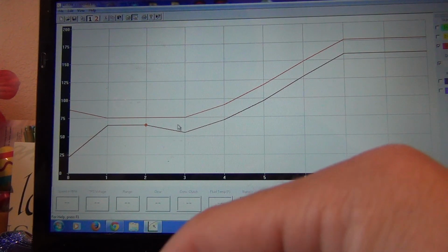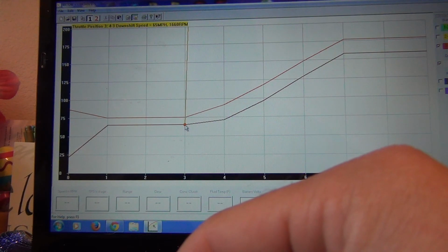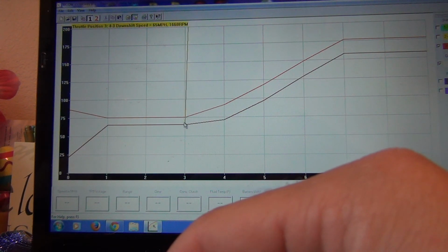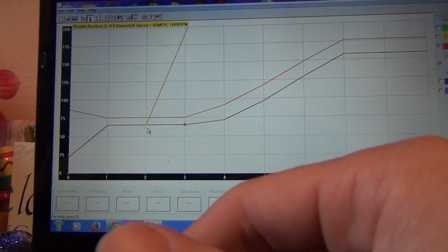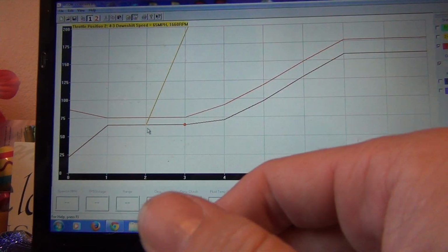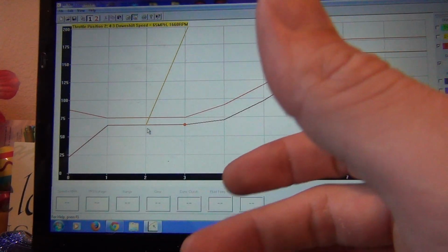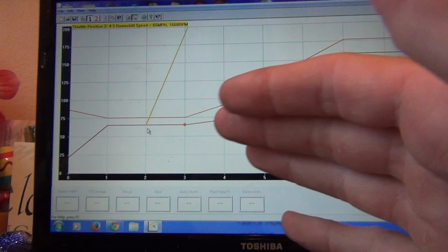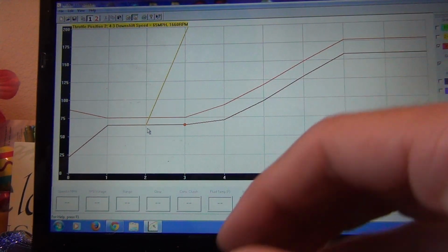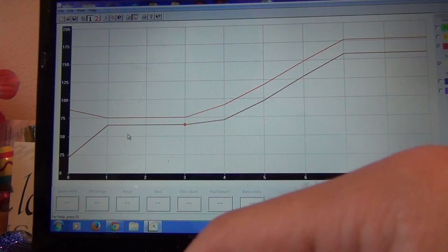And the reason why is, like I said, if you get stuck behind someone, so your engine doesn't bog down, you want it to switch sooner rather than later. Because the issue that I had the other day, like I said, I'm doing 50 miles per hour and this thing was lugging my engine down so far it backfired, so I had to slow way down just to get out of overdrive and then speed back up.